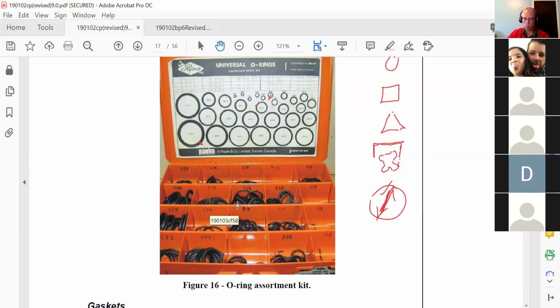Either they're made of the wrong material or they're not cut to exactly the right size that you would need. So potentially the cut thing could be true, that they're not the right size. O-rings, it's almost like a Society of Automotive Engineers thing, or like a universal standard, the sizes. So they might not mess around with that, but the material is the big one.